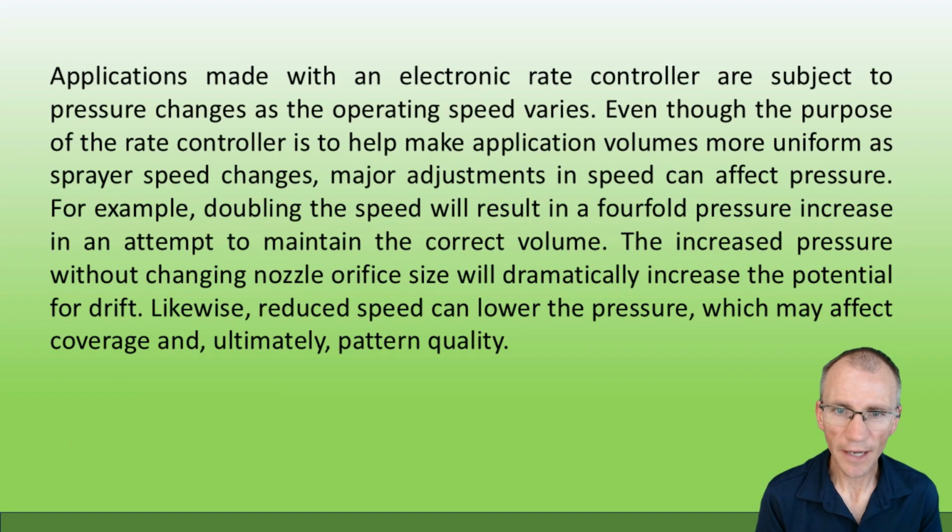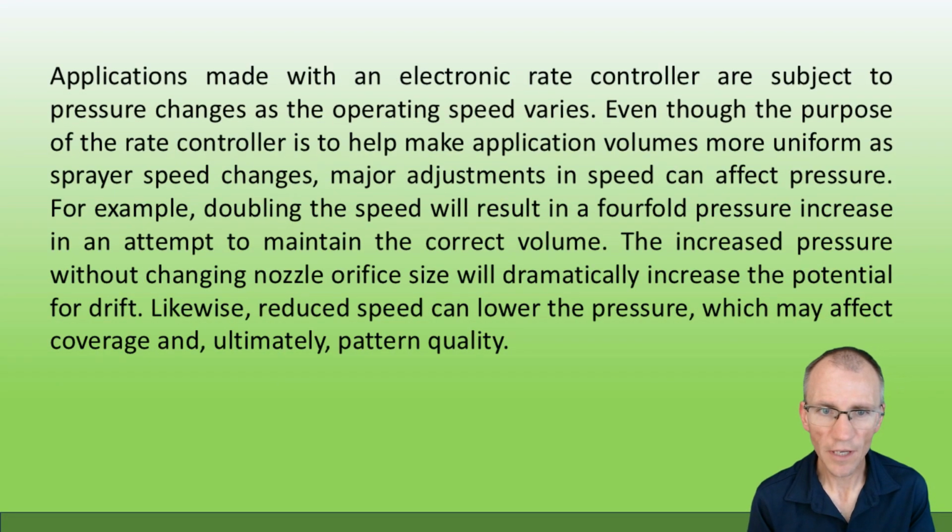Applications made with an electronic rate controller are subject to pressure changes as the operating speed varies. Even though the purpose of the rate controller is to help make application volumes more uniform as sprayer speed changes, major adjustments in speed can affect pressure.